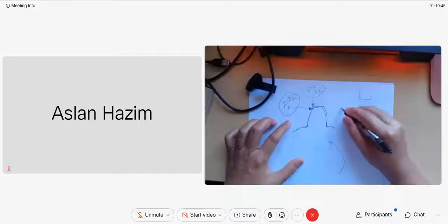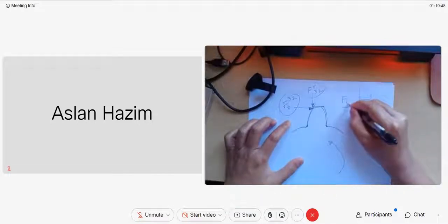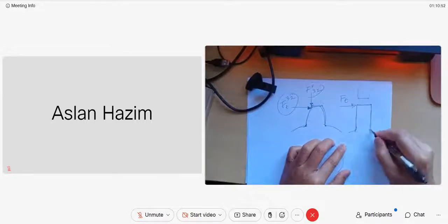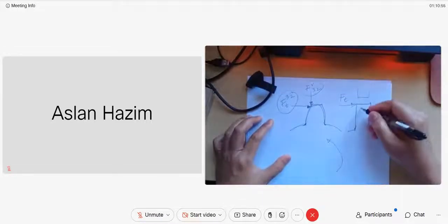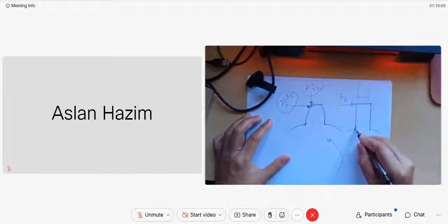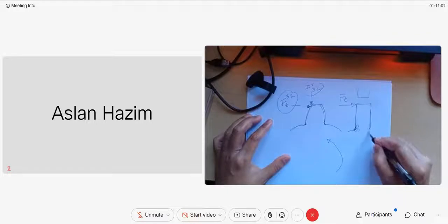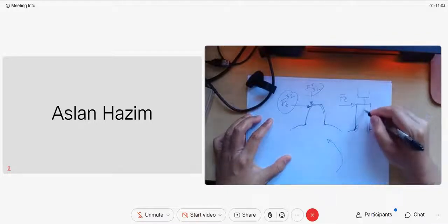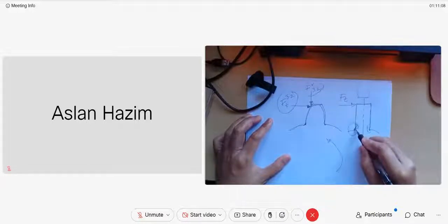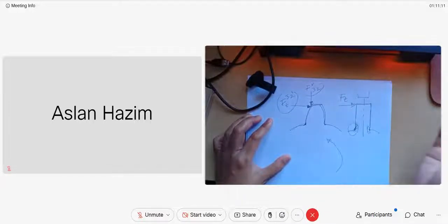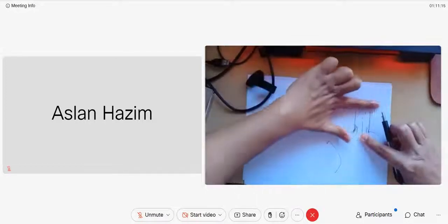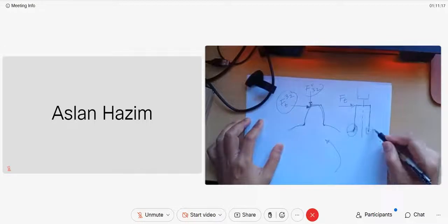Consider then you have F tangent like this, F tangent on the cantilever. And this one is a fillet, right? So if you have F tangent on your cantilever beam, it will cause bending stress here, at this neck. If this is the neutral axis, this side will sustain tension, and this side will sustain compressive stress. The value is the same, but because F tangent is like that, this will produce tension and this will go for compression.